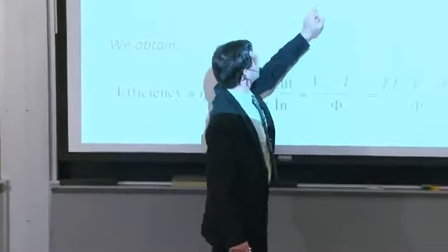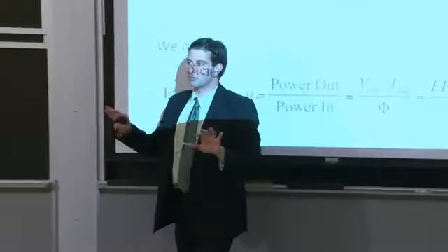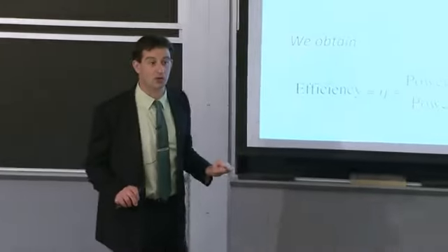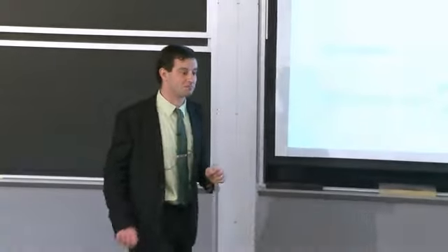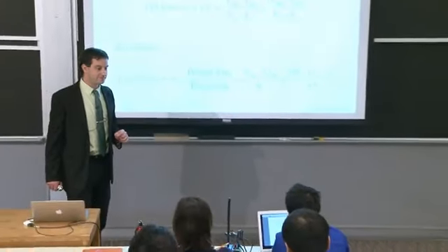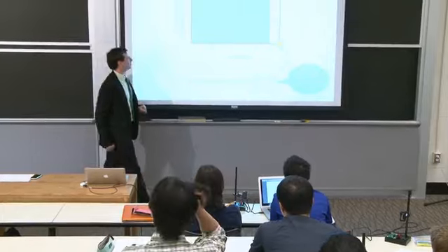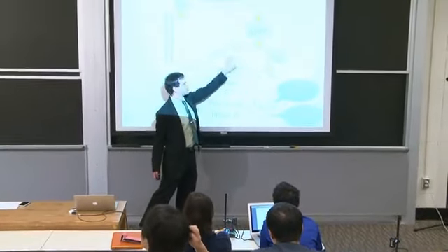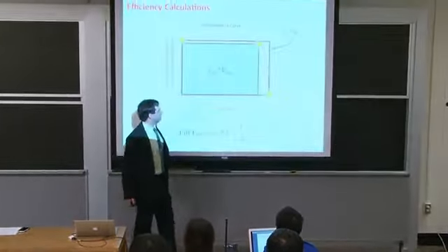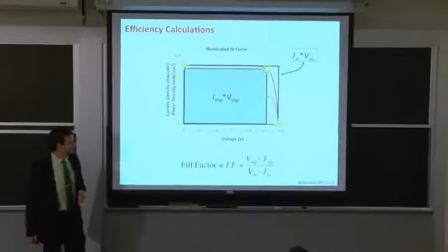If we have everything lumped in terms of VMP, IMP, it becomes a little bit more obscure to figure out what exactly is going wrong with our solar cell device. Ashley. How do you, I guess is the fill factor also an easily measurable parameter? So the fill factor you would measure essentially by doing the little analysis we just did right here. Yeah, exactly. So you'd have to do a voltage current sweep.